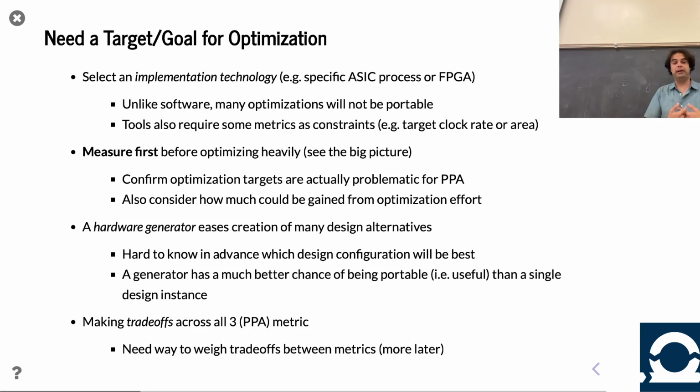You've seen examples already of us doing recursive things to build topologies internally based on those parameters, versus in Verilog, where you're constrained to things like a genvar. And for those of you who are Verilog experts, I know this may aggravate you, but I'm also constrained to things that are synthesizable. There's plenty of things you can do in SystemVerilog simulation that we're not even talking about right now. But more generally, it's not so much the parameters; it's the programming language that glues it together in Scala that lets you do all sorts of cool things.